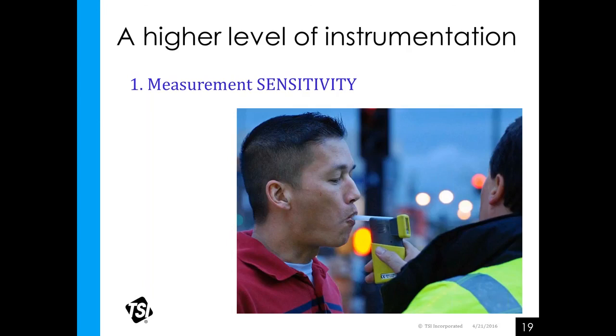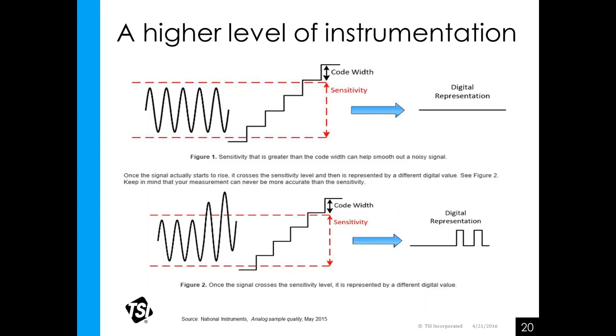Second thing, talking high level of instrumentation, I grabbed two charts from National Instruments. I think oscilloscopes are a really good representation of any instrument when talking about sensitivity. They use the term code width, and that's really the discrete level at which the instrument displays values. The resolution defines the code width. So your sine wave there is really where that sensitivity for that instrument lives.